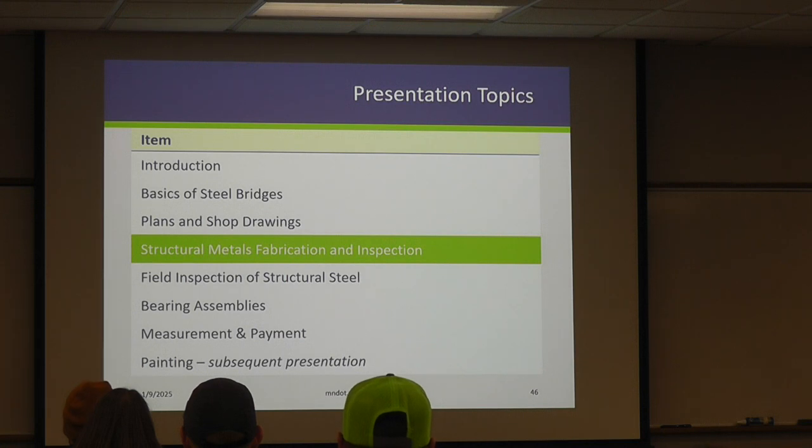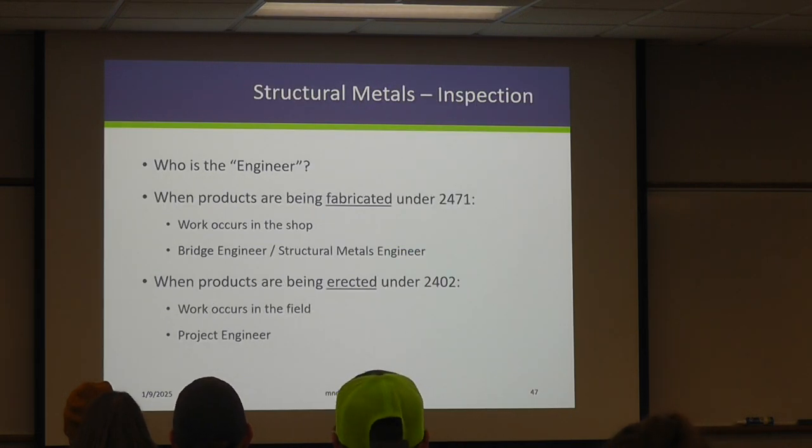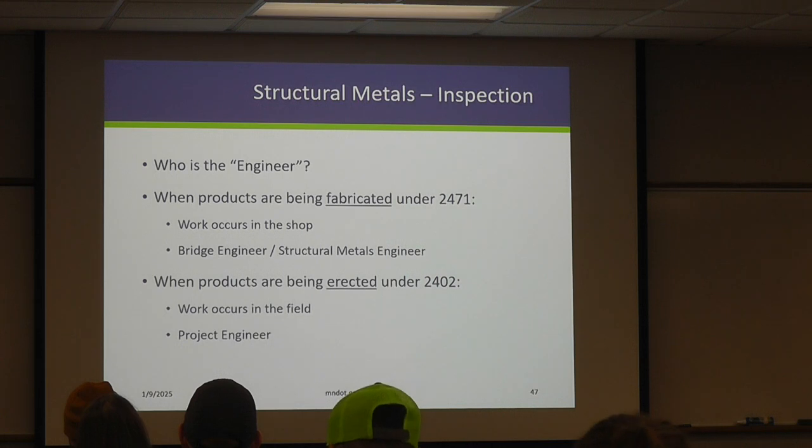So, once the shop drawings have been approved, the fabricator is going to work on creating these elements. And there's a whole series of inspections, quality control, quality assurance that has to take place before those elements are ever permitted to leave that facility. So we cover this in two different areas of the spec work, because we have the work that you folks are going to be tasked with out in the field versus all of this work that has to happen in the shop. And so sometimes this gets a little bit confusing for folks.